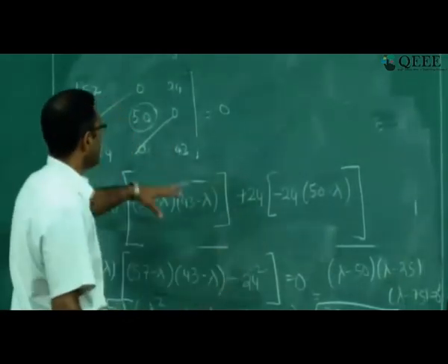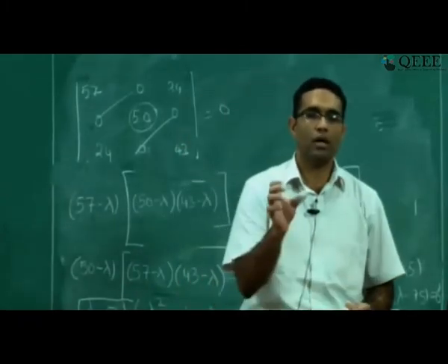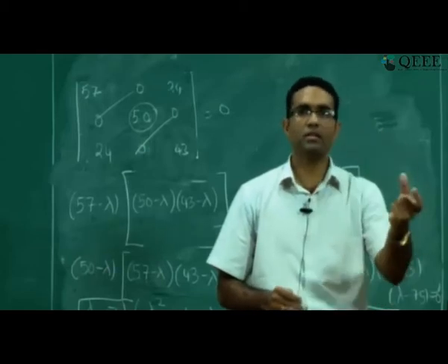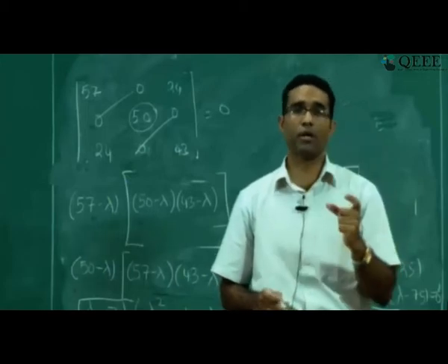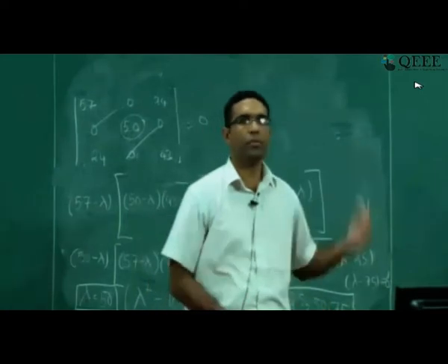You have to find the principal stresses, which will be 25 and 75 respectively. So in this way, you can find out the principal stresses of a given stress tensor, number one. Number two, the invariants: not only is it important to write the characteristic equation, the invariants play a very important role in failure theories also. So let's just continue with the same problem that we have been looking at. This was the stress tensor that was given to you, and we wanted to find out the principal stresses. Sometimes by just looking at the stress tensor, you will be able to identify one or two principal stresses.